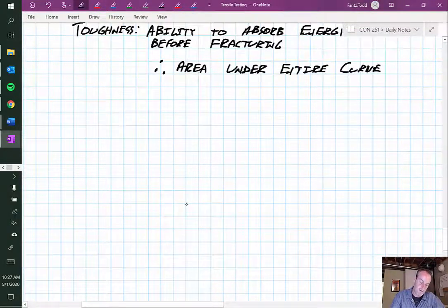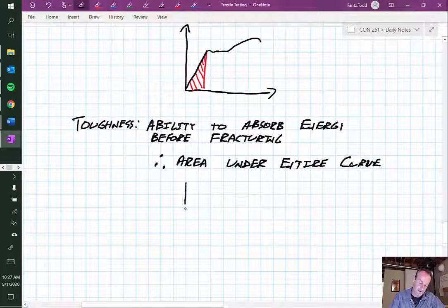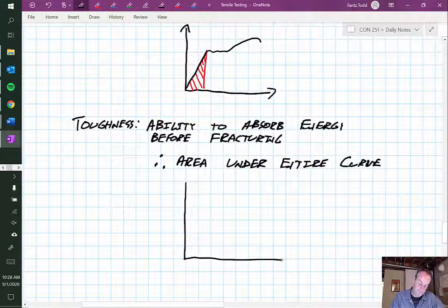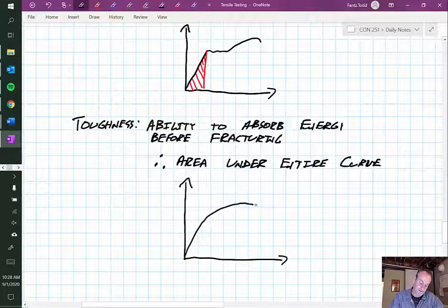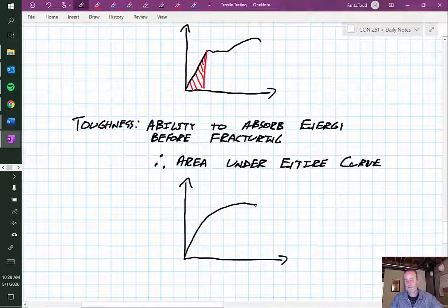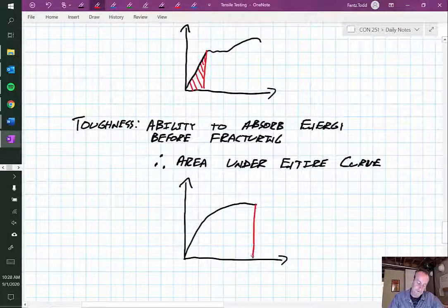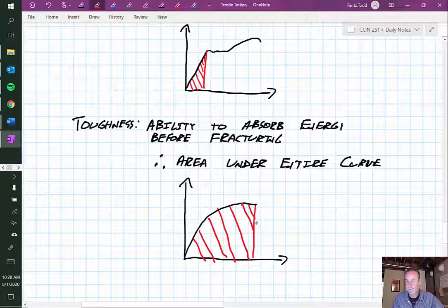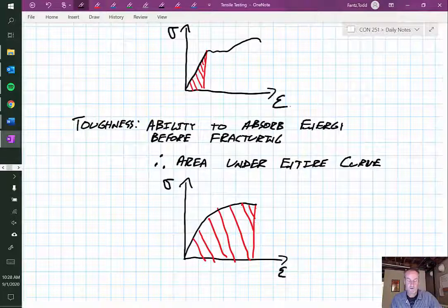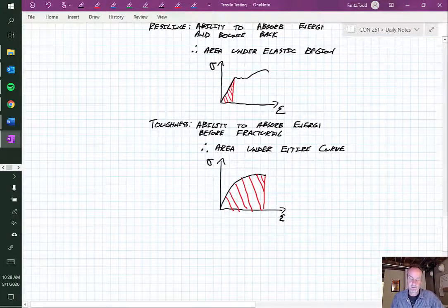If I were to draw that out and look at our stress strain diagram, say, of concrete. We haven't talked about concrete much. Concrete actually looks more like this. It's pretty cool. It just doesn't have as nice of a linear section. The whole thing is moving around. But when we're talking about the area for the toughness of, say, concrete, it'd be that entire area underneath the curve. All right, so let's take a look at a quick example.